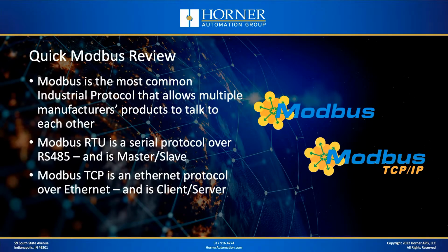Now, if you want to communicate serially, in other words, maybe you've got variable frequency drives or other devices whose Modbus data is available serially over RS-485 or RS-232, then you're going to use Modbus RTU or Modbus ASCII, one of the Modbus serial protocols. That is a master-slave type protocol. If you're talking about sharing data over Ethernet with multiple industrial devices, now you're talking about Modbus TCP, which is